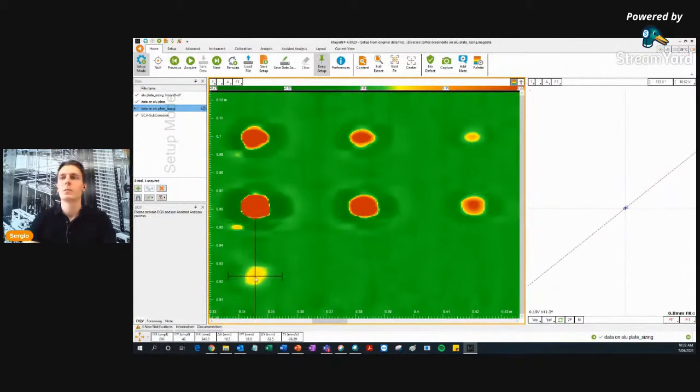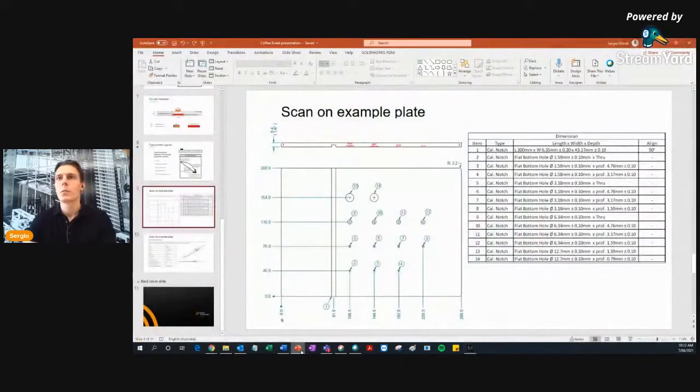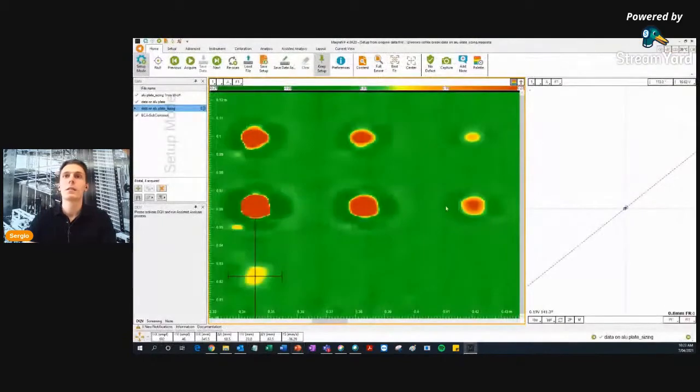Oh, I didn't show you this one. It sizes me 0.8 millimeter, and it's actually 0.79. So that's not too bad. There's a certain amount of liftoff where we will lose the defect, and you won't be able to size it anymore. But we can tolerate up to a few millimeters of liftoff, and still penetrate like 75% of the material.